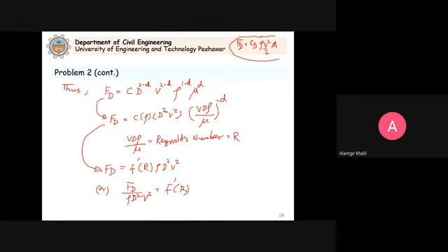And this is a function of some coefficient. Actually, we know that that coefficient is the drag coefficient, and that coefficient is a function of the Reynolds number. This is what the dimension analysis is telling you. What we studied there is that CD is a function of the Reynolds number. And we studied the graph for 3-dimensional and 2-dimensional objects, the drag coefficient versus the Reynolds number. So you can see that dimensional analysis is very helpful.